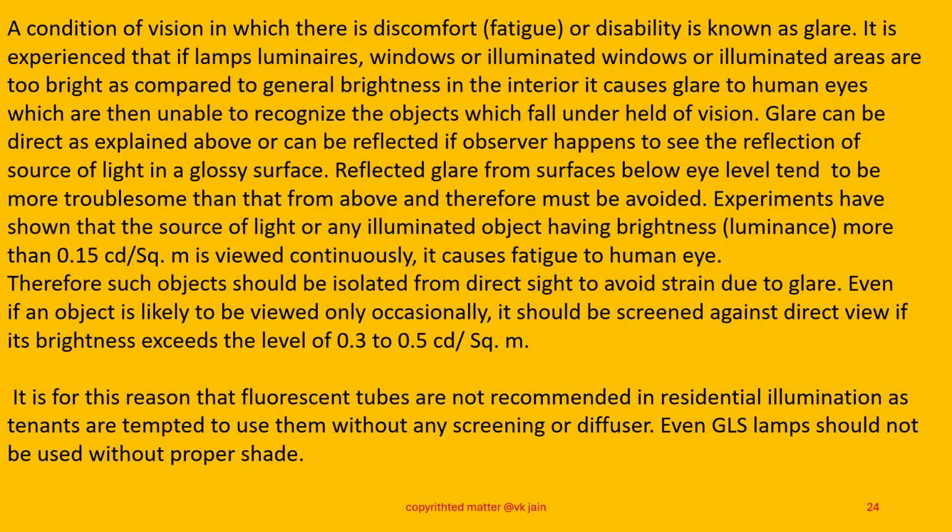Friends, a condition of vision in which there is a discomfort, that is fatigue to the eye, or disability is known as glare. It is experienced that if lamps, luminaires, windows, or illuminated areas are too bright as compared to general brightness in the interior, it causes glare to human eyes, which are then unable to recognize the object which fall under field of vision.